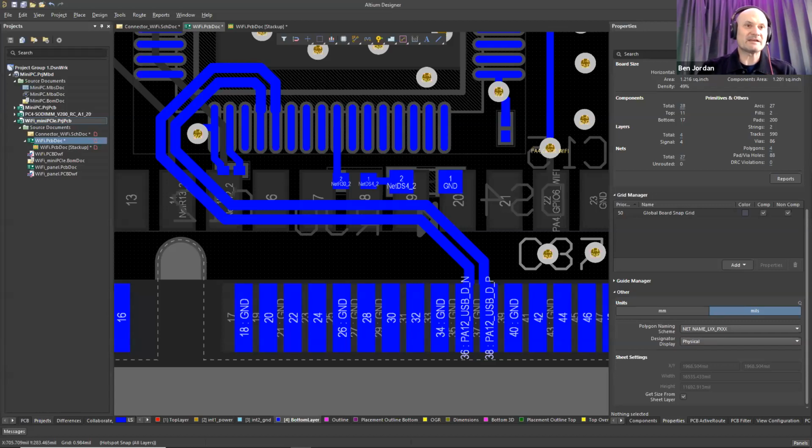Some specific materials for RF and microwave design do have more of a variance, where there's an optimum region in frequency, and you want to be super accurate to create exactly the right shape on the board for an RF filter or something like that without shifting your center frequency or bandwidth too much. Then yes, you really need to care about whether DK and DF change significantly over frequency. So I'm hoping that we add that in a future release, but at the moment it's just a single value.